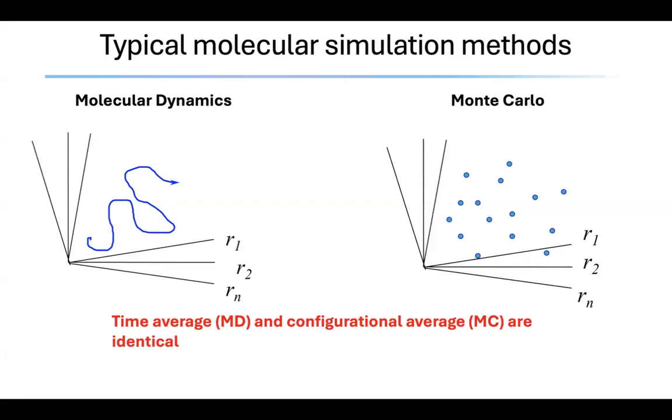So this is a good check to see if both of your codes give you the same set of properties for a given system. If you're choosing to calculate the density of hydrogen, like I said, at 5 megapascal and 348.15 Kelvin, it doesn't matter whether you do molecular dynamics or Monte Carlo, you should end up with the exact same density, given that you run your simulation for a long enough time.